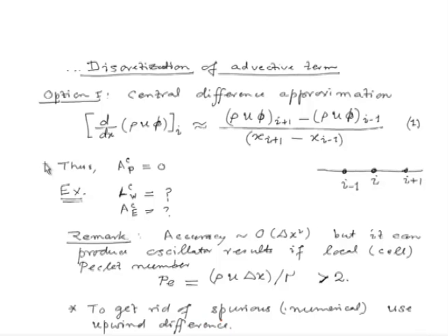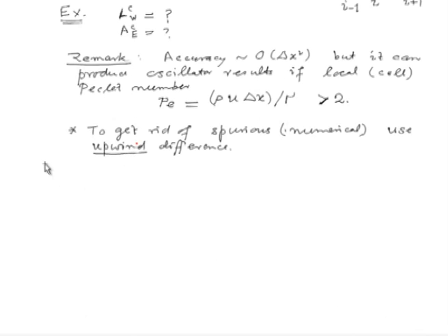Now, here we have used the term upwind. What do we mean by upwind? Upwind comes from the normal connotation of when we say the wind is blowing. So, this is an advection-diffusion problem, and the advection depends on the velocity. Suppose we just focus on a specific point in space, it could be a grid point I. Look at the velocity here.